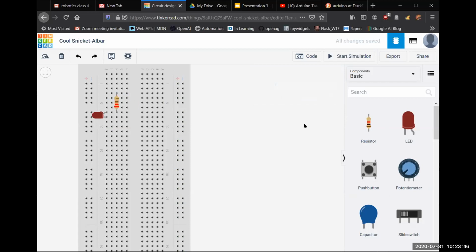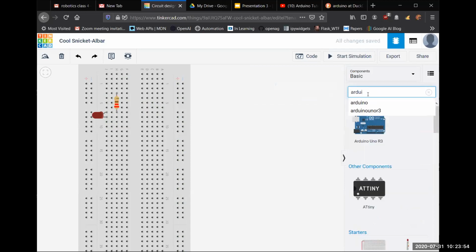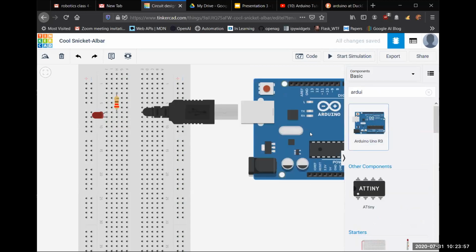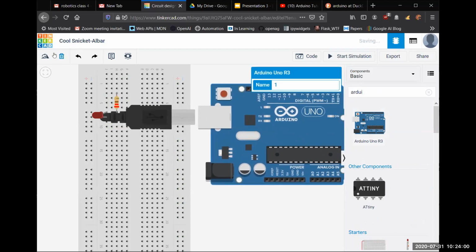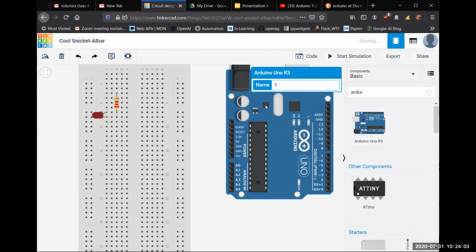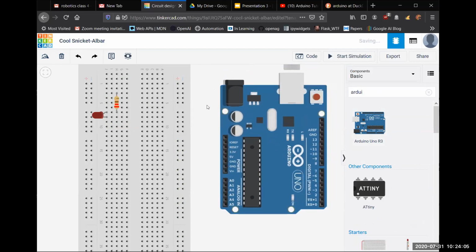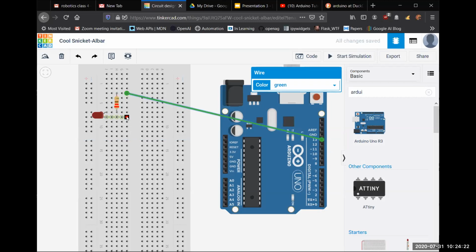Then the next thing after doing that will be getting the Arduino. Okay, so that's this one here. Also make sure you're checking the colors. In the example we did, we were using the digital pins. So make sure you connect one from 13 and then it goes to the LED pin, and then the next one goes from here to here.